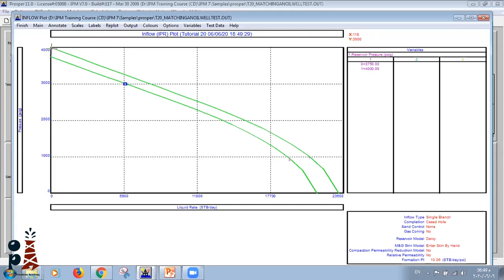So I found that in order to have this rate, there's a reduction in the reservoir pressure to be like 3,750. So if I have this reduction, I go to the reservoir engineer and I speak with him, and I ask him if the reservoir pressure has already decreased. So if there is a reduction, then it's normal.